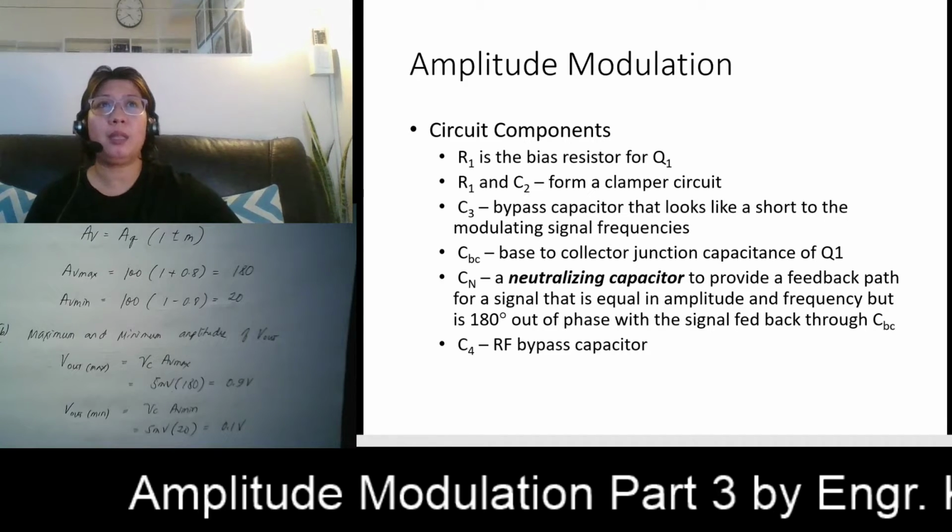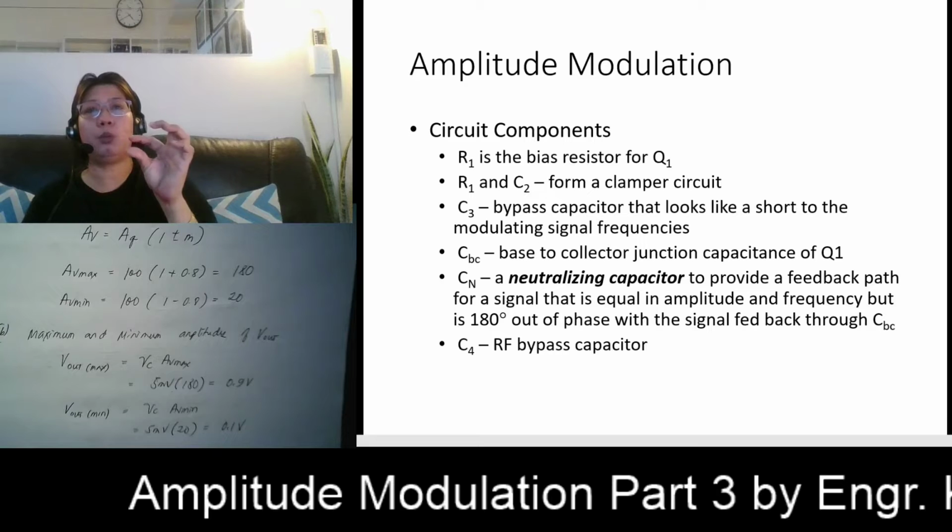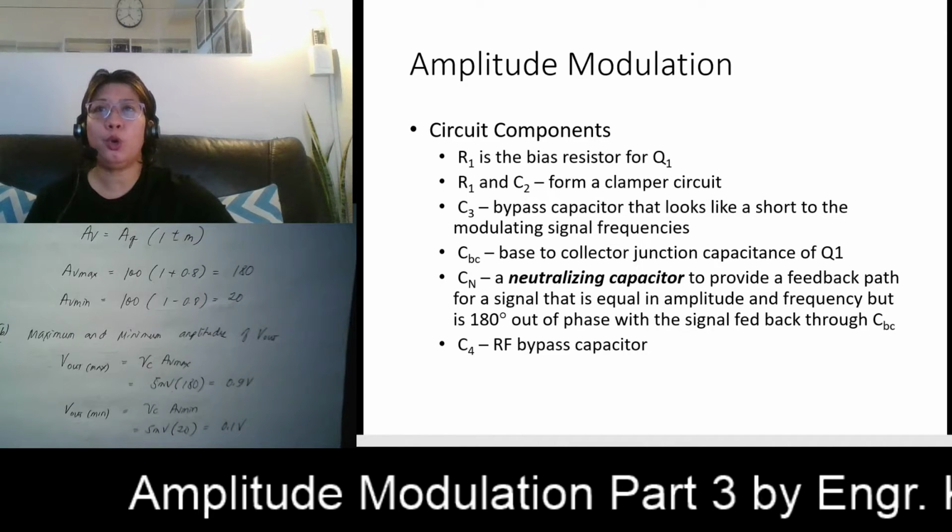It is the one which produces the 0.7 pulses. Q1 can be biased to turn on only during the most positive peaks of your carrier voltage, those voltages above 0.7. It produces a narrow IC, or collector current waveform, and enhances Class C efficiency.